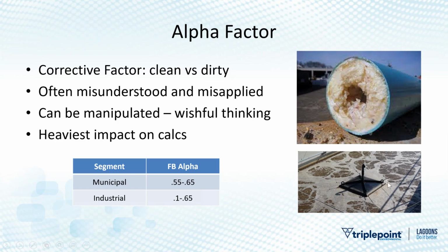You measure the concentration of oxygen at that site, so you know exactly what you're pumping down in there, and then you measure the concentration of the oxygen coming off of the off-gas, and you find the difference. Then you can calculate the transfer rate in your water with whatever equipment is being put in there very, very accurately. So this is a great diagnostic tool to find out, why don't I have enough air, or how much air do I need, and I don't want to screw this up.